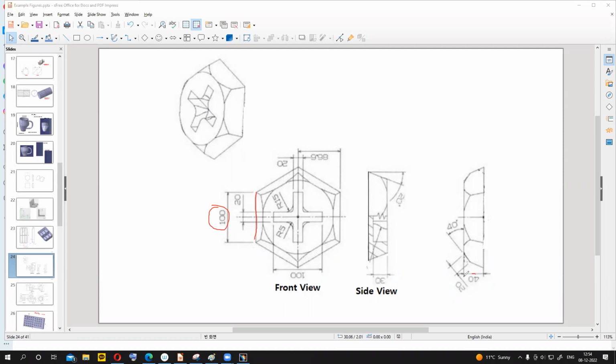And pad 40, and later we use edge fillet, draft, okay, with an angle 20, all the sides of hexagon, and make a chamfer. Okay, so create chamfer here, chamfer here, chamfer here. So to do that one, we create a triangle on the plane crossing these two corners, and groove it. Okay, and make this one and use variable radius.